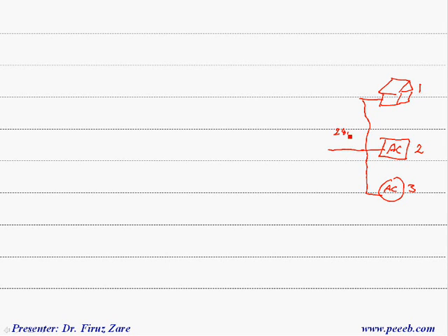So finally, this is the power system. That means for these three different types of loads, load 1, 2 and 3, these are connected to this AC system, which is basically 240 volts and 50 Hertz, through this output filter, and this filter is connected to a high power DC to AC converter, and the voltage at this terminal is, for example, 400 volts.